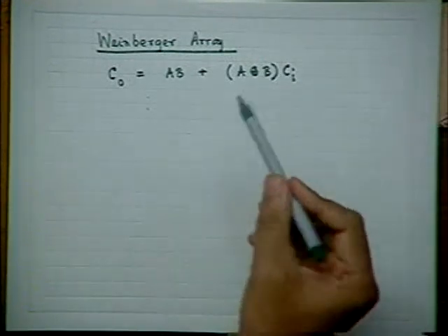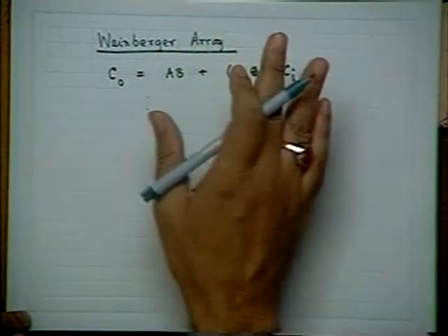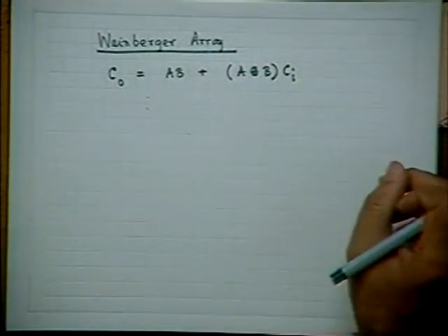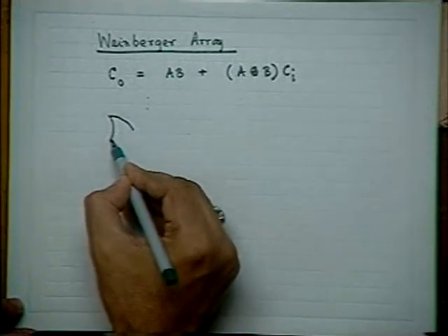And in that case, the simplistic way of drawing the block schematic of this is as simple. And normally, as you know, in MOS technology, NOR is simpler. NOR is most natural. Therefore, we shall try to realize everything via NOR. So you just do it. First, realize this one. So what you have to do, you take two NOR gates.